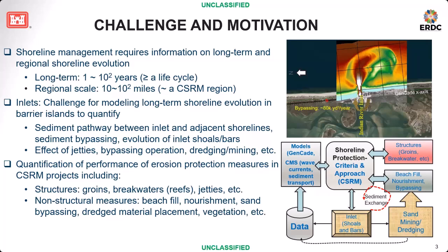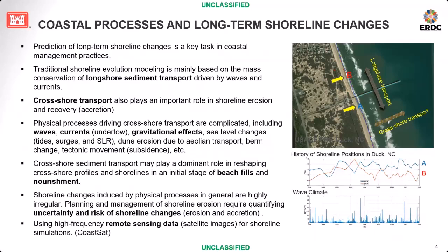Now we have more remote sensing data, so we can also use satellite imagery to extract the shoreline. We are right now doing those studies to implement a satellite imagery-based shoreline model. The traditional shoreline simulation model, the one-line model, is based upon highly empirical longshore sediment transport driven shoreline change, based upon the principle of mass conservation. But longshore transport alone may not be enough to explain